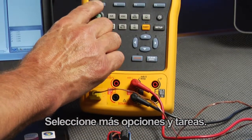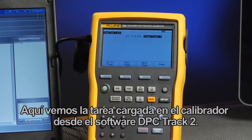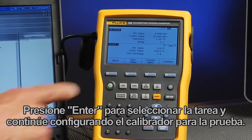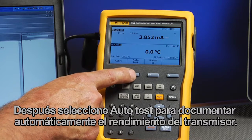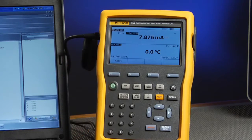Select More Choices and Task. Here you see the task that was loaded into the calibrator from the DPC Track 2 software. Press Enter to select the task, and then Continue to configure the calibrator for the test. Then select Auto Test to automatically document the performance of the transmitter.